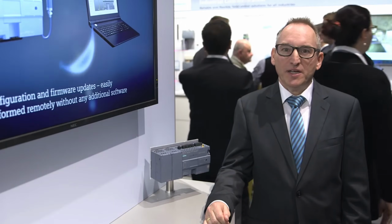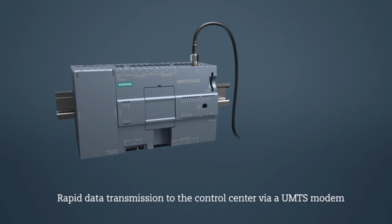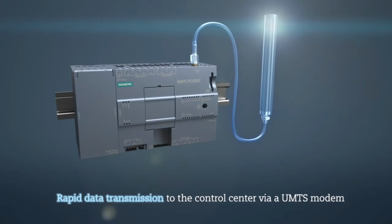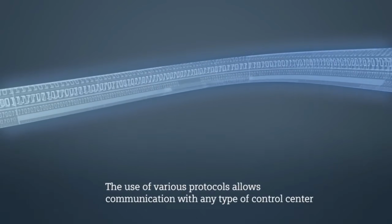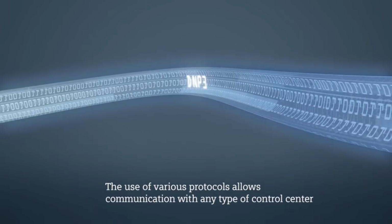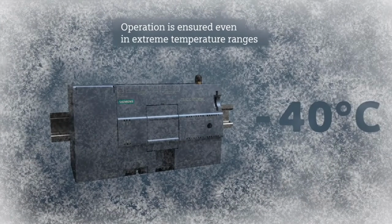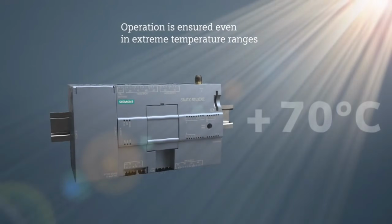A web-based management allows for easily setting all necessary parameters for the sensors, update times, communication parameters, etc. All measurement values are assigned a timestamp, are buffered in the RTU, if needed, and transferred to the control center via the integrated UMTS modem. The RTU 3030C supports the different telecontrol protocols, Telecontrol Basic, DNP3, and IEC 60870-5-104. A robust design of the RTU 3030C allows for the use under harsh conditions, ranging from temperatures of -40 centigrade to 70 centigrade.